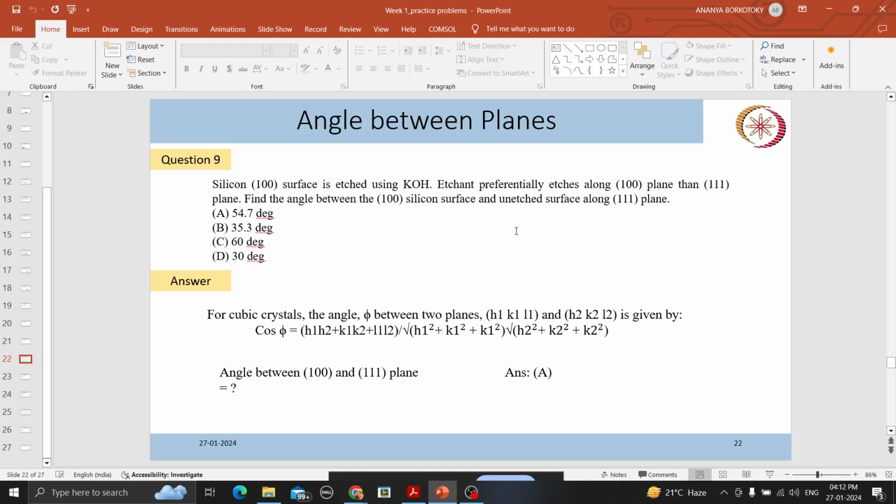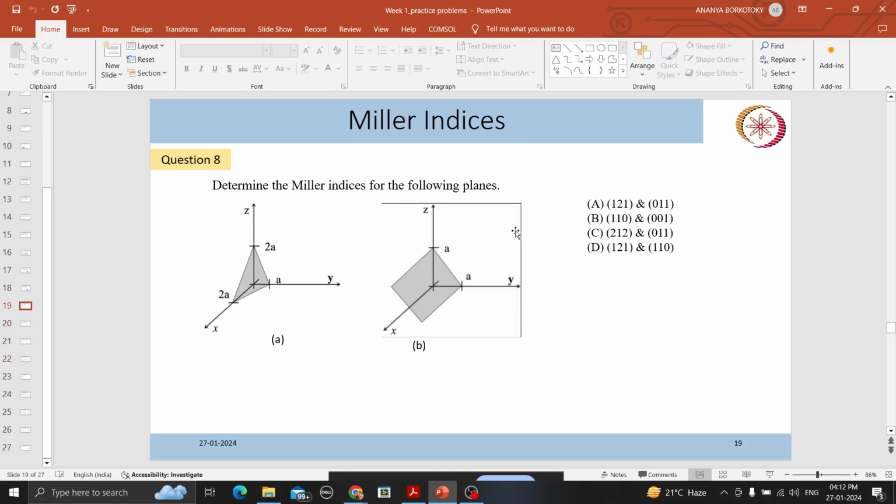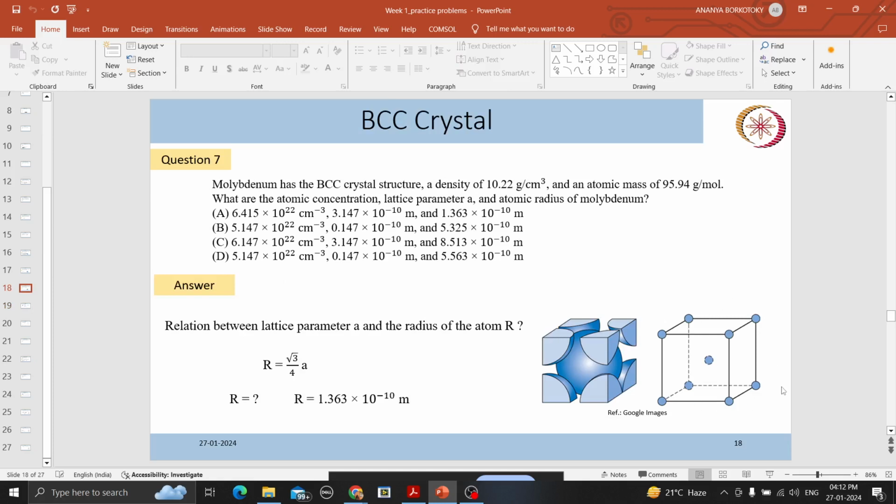It will be easier here. So this is a cubic crystal system. The 100 plane will be this front plane, right? And this is the 100 direction. So this plane and this direction are orthogonal. Now if we want to determine the angle between two planes, we can draw orthogonal lines to these planes. Suppose we want to calculate the angle between this plane and this plane.